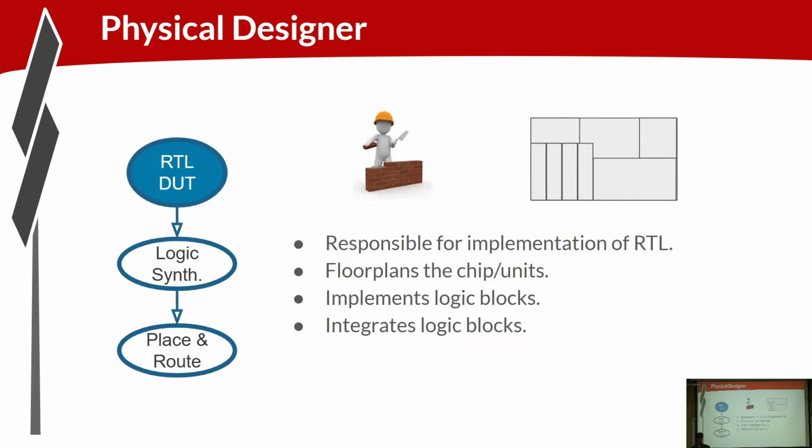And again, this is all iterative, right? So the logic designer is working on the RTL, the implementation team is running logic synthesis, place and route, they uncover timing issues, they uncover floor planning issues, they feed that information back to the RTL designer, and it's a lot of back and forth.